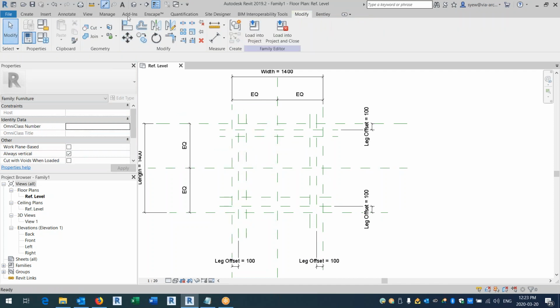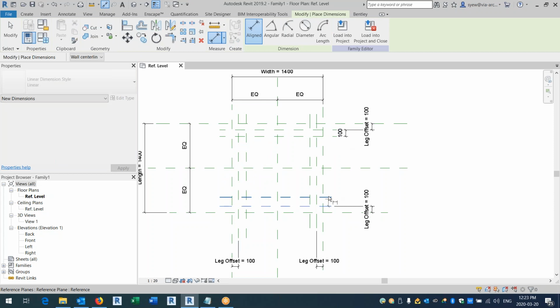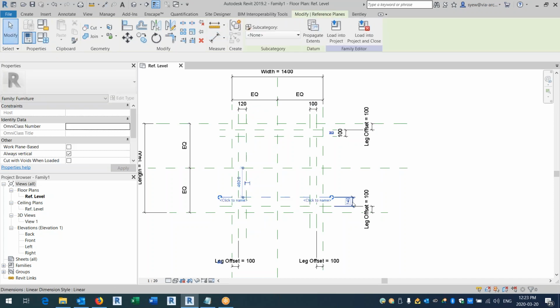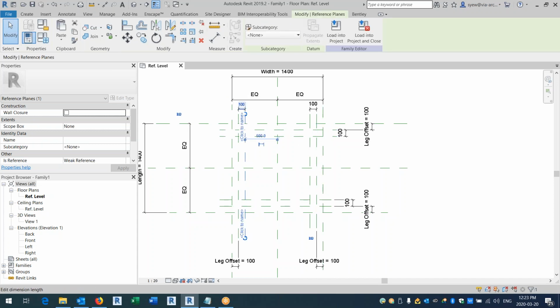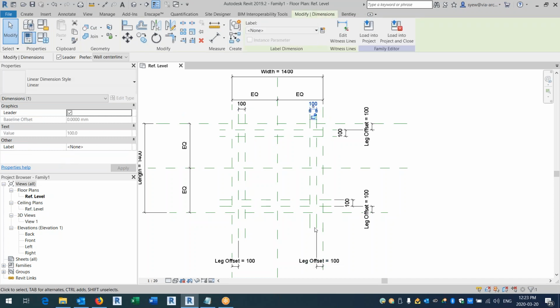I always like to create a skeleton first before I model it. The reason why is that it gives me an understanding of what kind of model I'm creating. So here, what I did is I'm creating a leg, basically a table that's hosted on here. So what I did is that leg offset allows me to offset it in and out. But later on, you'll see what I'm getting at. But for now, just put it in like this type of parameter pretty easily.